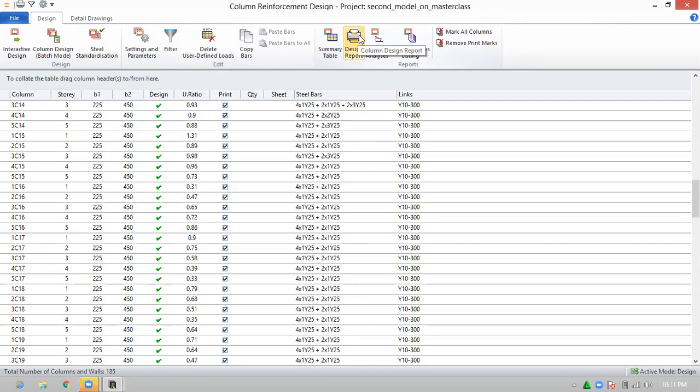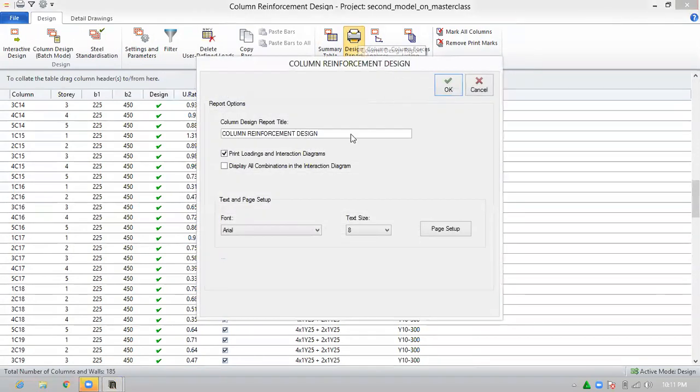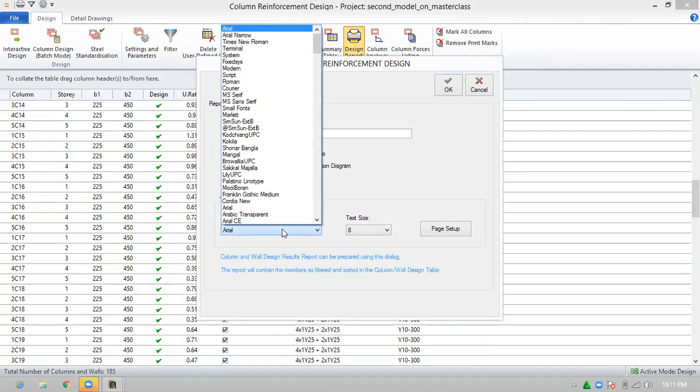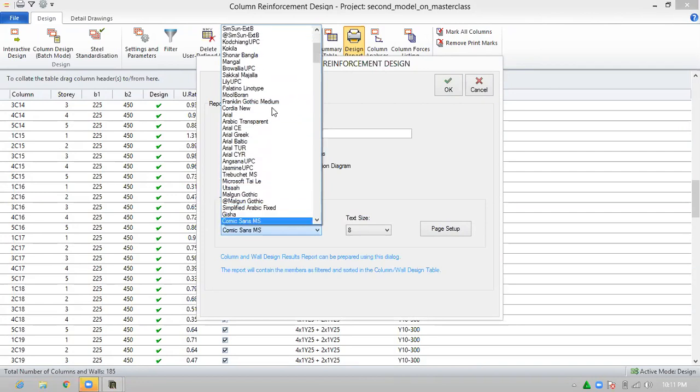You just click on design reports and I'll click on display. It will not show any beam or column that did not pass in the calculation sheet. Orion will not. That is one thing. I just want you to know about it.